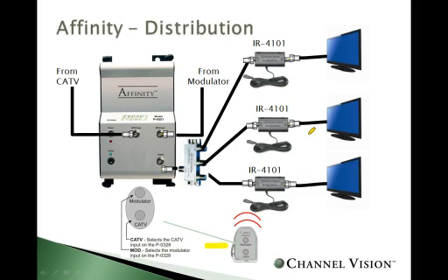Now for those of you taking notes, you'll note that there's not a two-way splitter in this application, and that's because there's no cable boxes at these televisions. Therefore, I don't need one. Simply select the input on the modulator button, select the modulated feed, and it'll switch your digital cable signal and allow you to view your cameras. Basically, it's a switch.